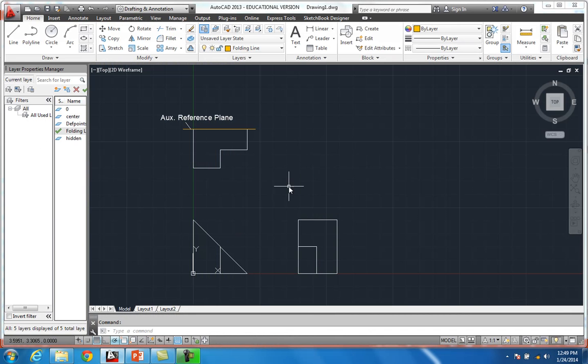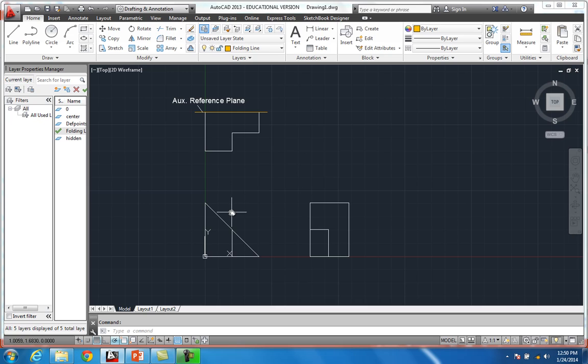I've got something set up here. It's a real simple little drawing. I've got the top, front, and right side, and I want to put my reference plane on this top side. No problem, right? All you have to do is throw yourself a line in here. Actually, it has to be parallel to that, so I'm just going to offset. Let's see where 1.5 gets us.